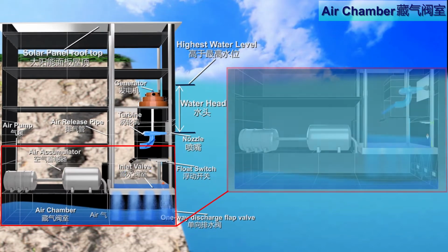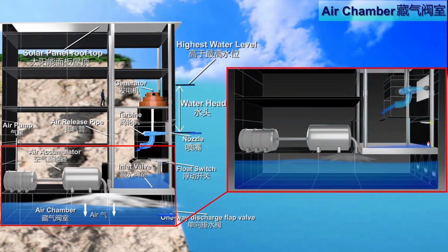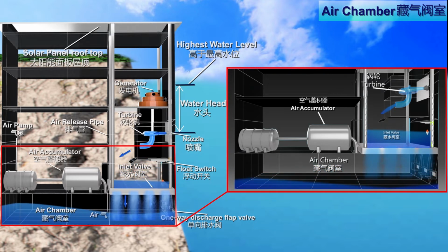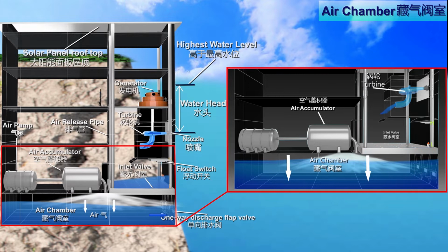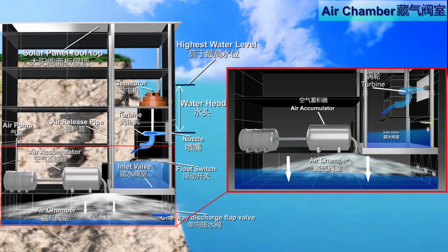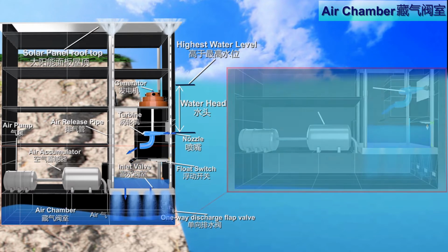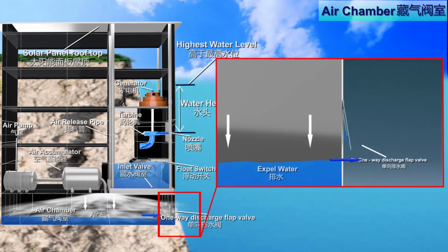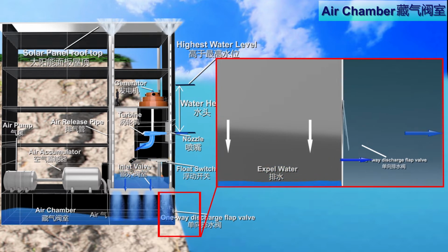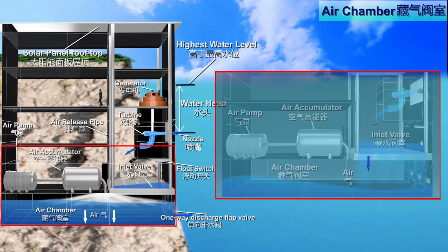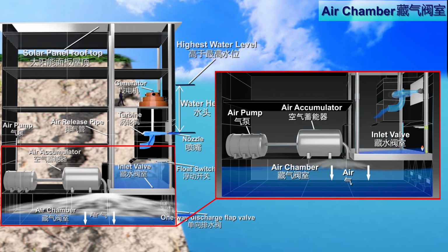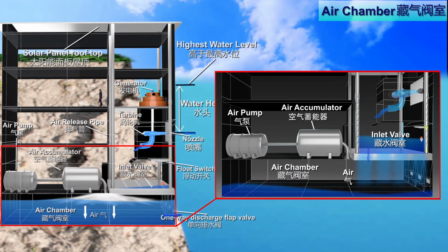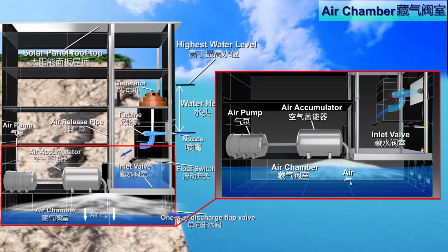An air displacement control valve is used to periodically control the compressed air supply into the air chamber and to periodically displace water from the air chamber through a plurality of one-way discharge flap valves, through which water is discharged out and any water tending to flow in would close the flap valve. With continuous charging of water inside the inflow dam, rotation of the turbine is non-interrupted and electric power generation is continuous.